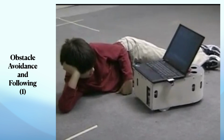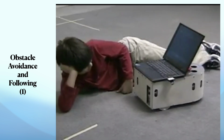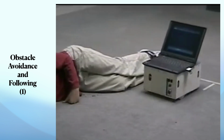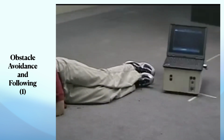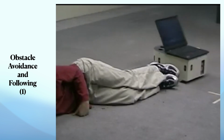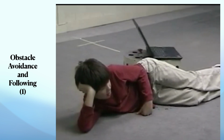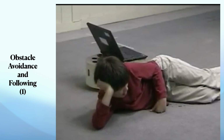Obstacle avoidance and following. 1. If an object has a concave envelope, the vehicle may find more than one tangent line on either side. In such a case, the vehicle can hug the object by successively tracking the shorter tangent line first. Andrew was never scared by the close encounter with the vehicle.